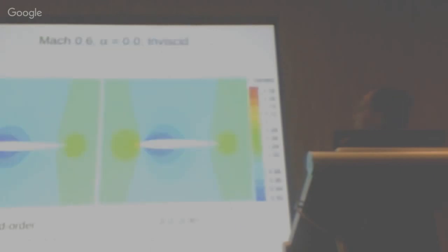These are just density contours. It's hard to distinguish with the naked eye what's different between one another, but you can see the entropy error is on a log scale. The Q1 mesh, the black line, actually has a higher entropy error than the quadratic mesh. So as I said, by going with also a high order mesh representation, you are better resolving, with a smaller error in entropy, which for a subsonic Euler case should be zero.